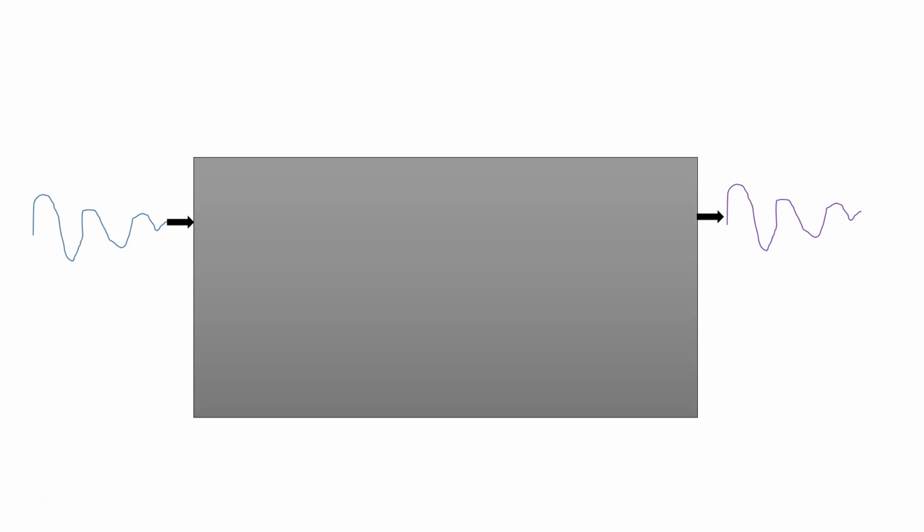We'll also, instead of using polling or interrupt, to move the data from the ADC data register to a memory, and later on from a data memory into the DAC's data register, instead of doing that using the CPU clock cycles, we'll use a direct memory access engine. So we'll use the DMA to transfer data from the ADC data register into an input buffer. We'll do some processing on that input buffer and move the output buffer into the DAC via DMA.